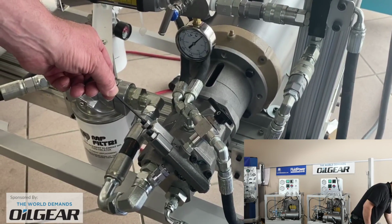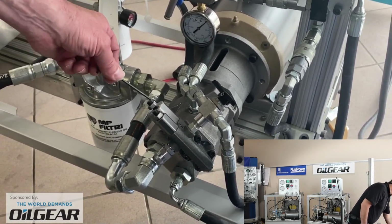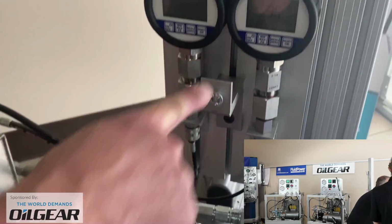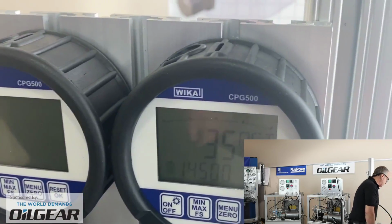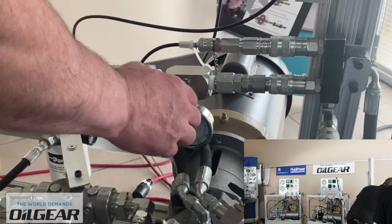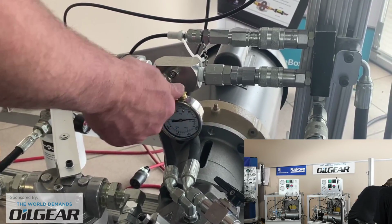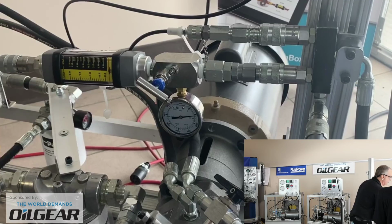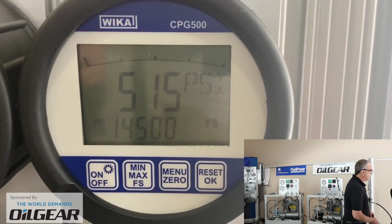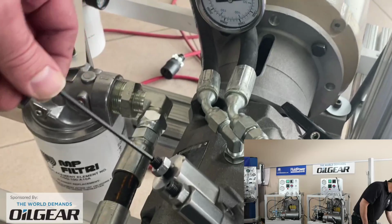As I take my trusty 3.5 millimeter, or my 3 millimeter key, to work on this particular adjustment, of course we're not in the right state. We have a free and easy flow path, so if I made any changes to the pressure compensator now, we'd find nothing happening on my pressure gauge. So I've got to blind out the flow of the pump by very gradually shutting in. Our flow rate drops off to 0, and we can see that currently our pressure compensate value is around 500 psi, and perhaps it's supposed to be closer to 750.